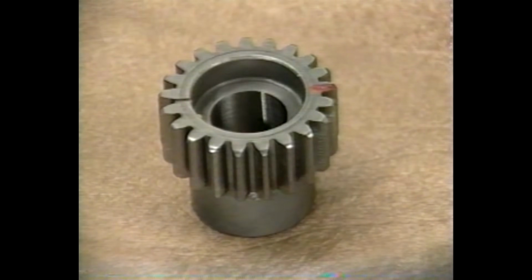It is not possible to place both of our dowel pins on the diameter of our pinion gear due to the odd number of gear teeth, so we place only 1 pin on the diameter. Now, the corresponding pin has to be placed on the opposite side of the diameter, but this point passes through a gear tooth, so we have to offset our second pin against this tooth, as shown in this diagram.